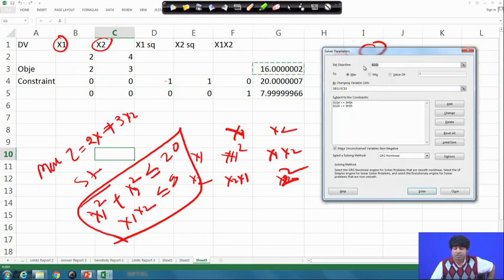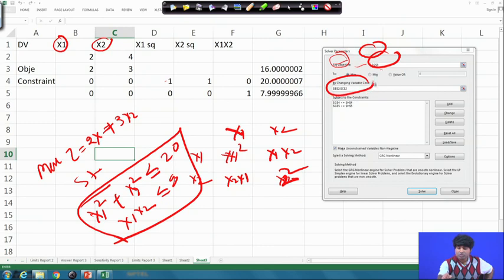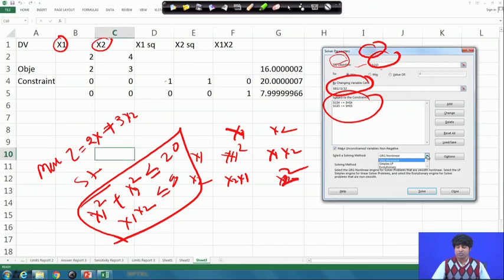So, we have given the indication about the objective function here. This is the objective function indication, this is the decision variable indication, and this is the constraints indication. And now there is no typical difference between linear programming and non-linear programming in the use of the solver package. Here we have the simplex LP format, and we have the NLP format. Now what will you do? Since our requirement is in NLP format, just put non-linear. After that we just put okay.